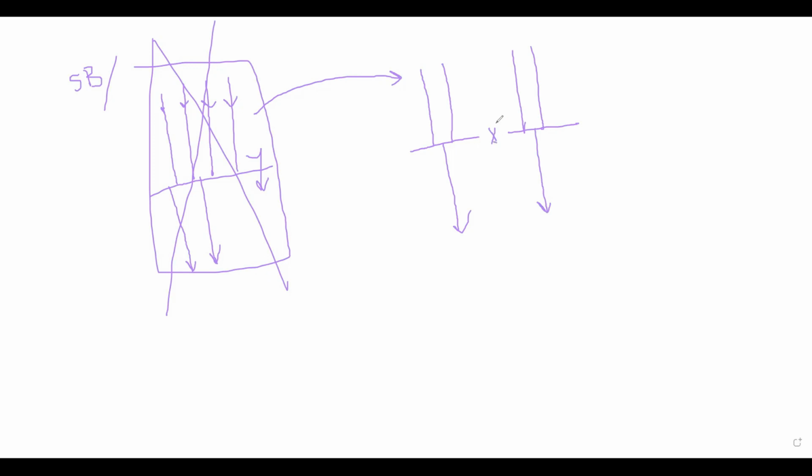Now, generally this will be in open condition. So he will export the power through this and he will export the power through this. Now, if this bus fails, only 50% of the power is lost. The other 50% is sent through this line. Suppose this line fails, then I will close this breaker and the entire power of 100 megawatt is flowing through this line. So this scheme we will call a single busbar with sectionalizer scheme.